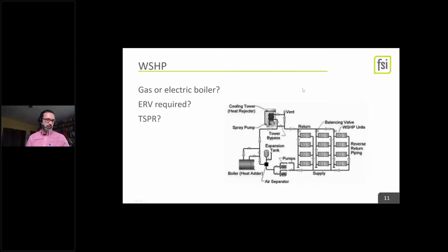And there are some fluid cooler requirements out of C403. But water source heat pump was kind of the go-to for extremely tall apartments, which is where they're mostly used now, but has otherwise been a go-to in the past for all sorts of things. So you might choose to keep it. It's an effective system, particularly if you can get the boiler to something else.